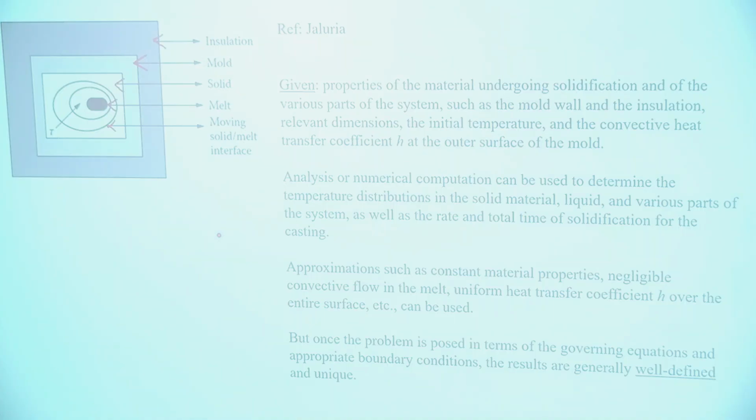So this is a production engineering problem that we know, but one interesting thing about production processes is that even though we say that is production engineering, this is thermal engineering, obviously there is a lot of thermal engineering in production also, right? So the molten metal will start solidifying. This part will solidify first, right? Then the central part is more like molten, right? And so this is kind of molten metal. This is solidified metal, and between them you have a zone which is a mix of molten metal and solid, and which is progressively getting solidified.